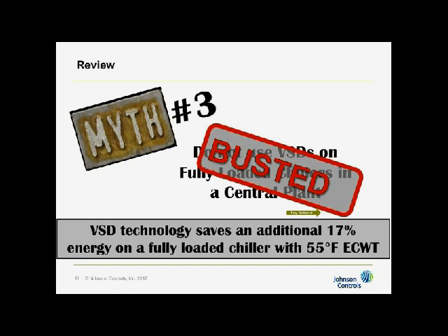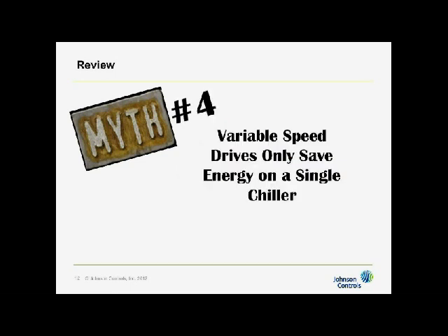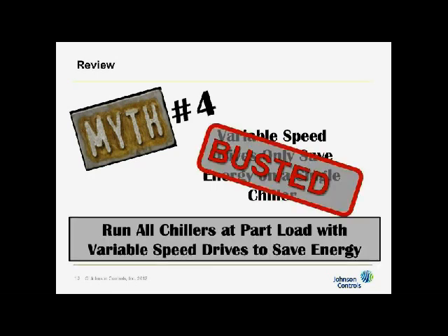Myth number 4, variable speed drive only saves energy on a single chiller. Well, if you remember from the myth a couple of times ago, a couple of bullets back, having heavy loads on chillers does not preclude saving money. But running all your chillers at part load is better when you have variable speed and you have low head.